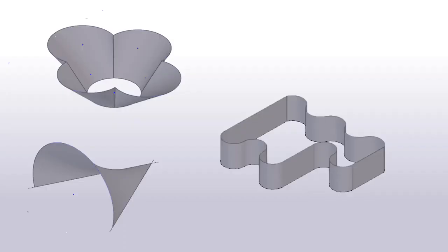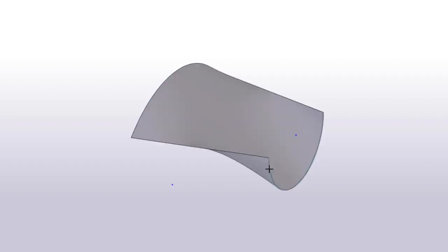Use the Create Lofted Plate command to create complex steel plates, such as rolled plates and plates with double curved form. Before you can create lofted plates, you need to have suitable construction objects in your model. This is because Tekla Structures creates the lofted plate by connecting the start point of the first construction object to the start point of the second construction object. The endpoints are connected in the same way.